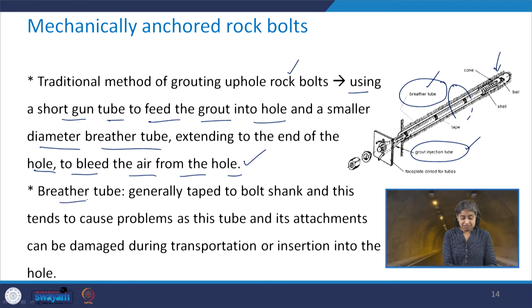Basically, this breather tube is generally taped to the bolt shank, which is here. And this tends to cause problems because this tube and its attachment can be damaged during transportation or while inserting the rock bolt assembly into the drill hole.